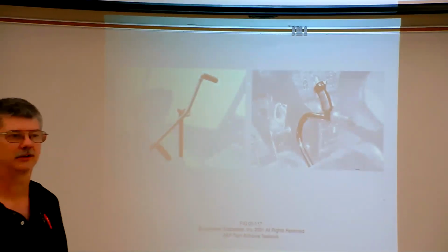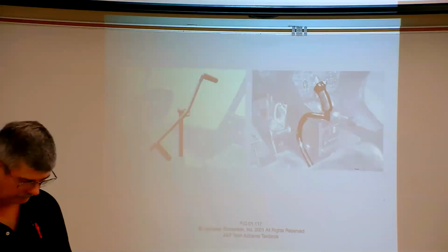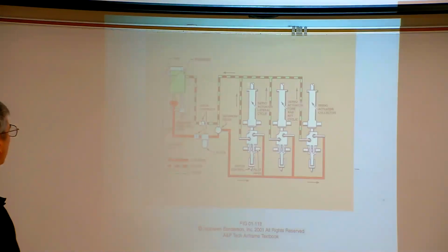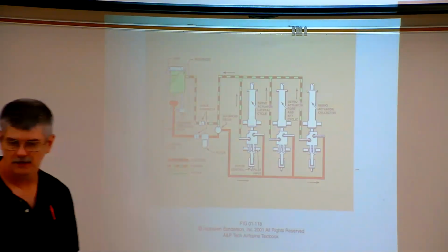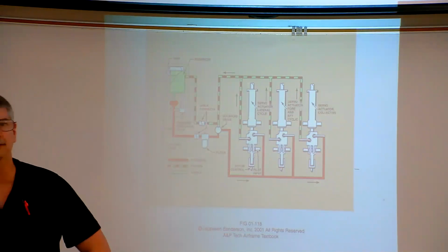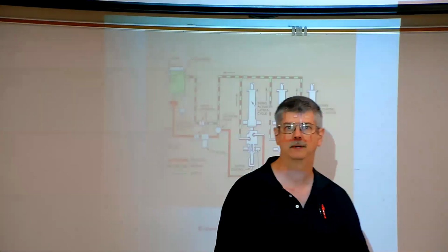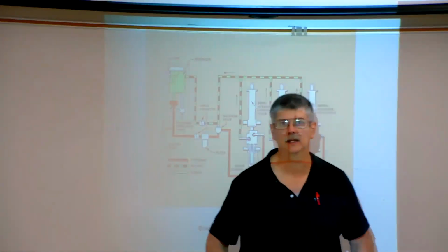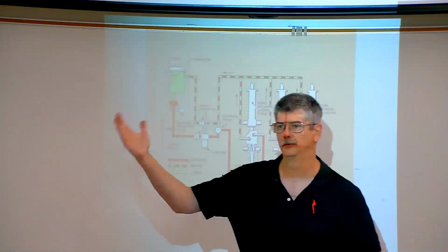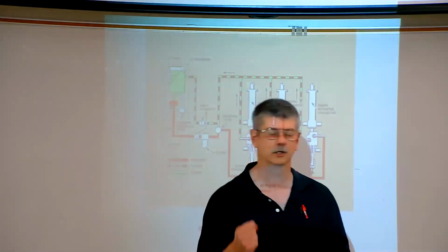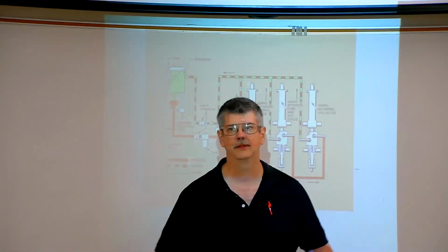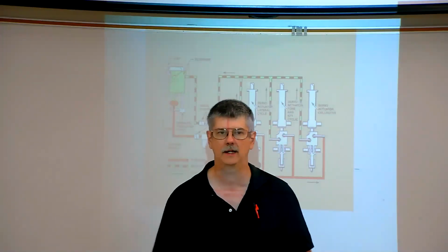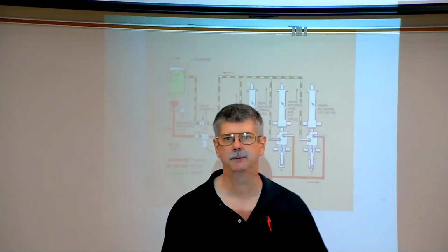Most helicopters are designed to be flown from the right seat. All right. Cyclic pitch, synchronized, okay, boosted controls. All this is that, you know, very small helicopters just have mechanical linkages. It's very similar to, let's say, the Cessna 150's rigging. The pilot pulls back, it pulls the cable, moves the elevator. On a helicopter, we move the cyclic. Generally, there are push-pull rods that then move the swash plate, all mechanically, all by the force of the pilot.